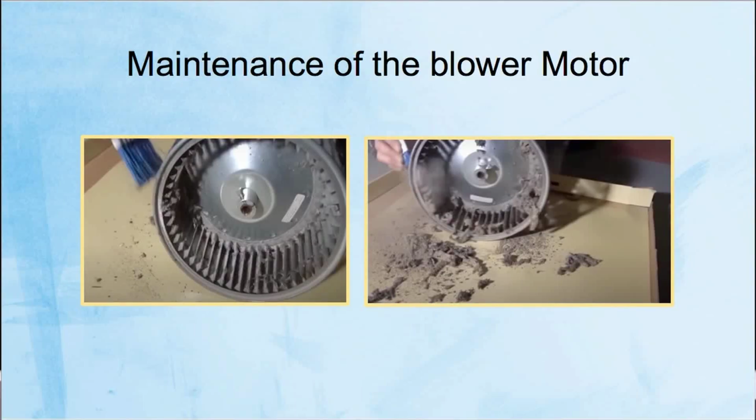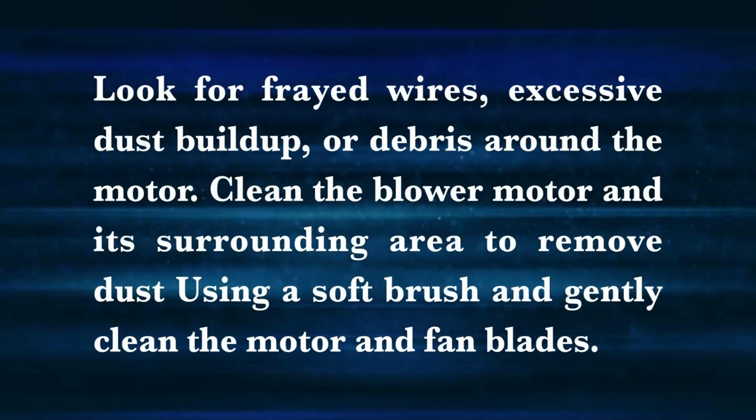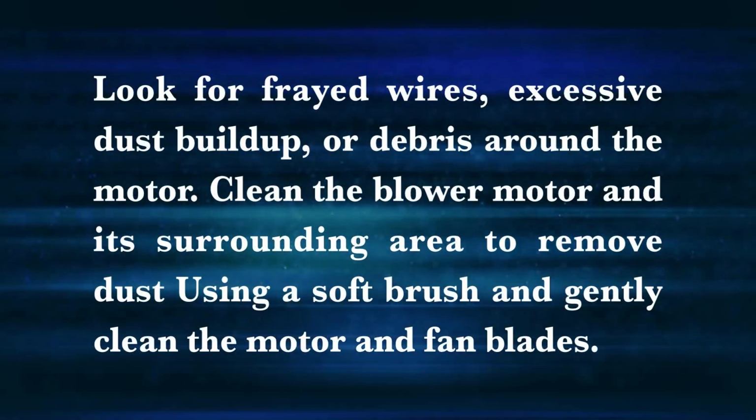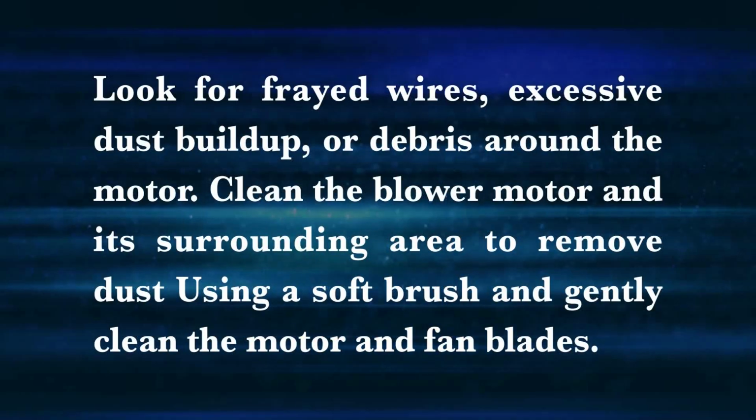Maintenance of the blower motor. Before performing any maintenance, always turn off the power supply. Look for frayed wires, excessive dust buildup, or debris around the motor. Clean the blower motor and its surrounding area to remove dust. Use a soft brush and gently clean the motor and the fan blades.